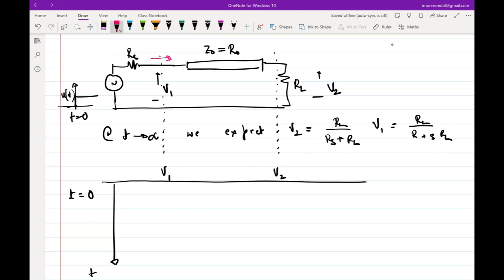And the transmission line, by the definition that we saw in the previous lecture, doesn't know whether the transmission line has an end or not, right? When the signal is at that junction, it is flowing through, it doesn't know what is at the other end of the transmission line. It is still evolving. The circuit is not yet settled. So for all practical purposes, you can assume that the transmission line may well be infinitely long, because it doesn't know what is at the other end.